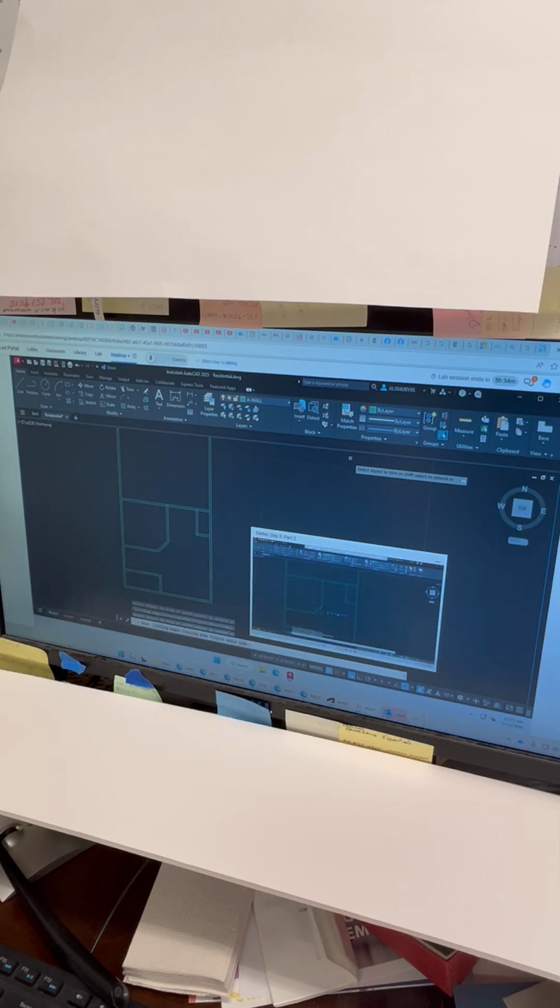Now here's why I did not want you to use the chamfer for the other caddy corner. If you tried to do that with the original 2 foot dimension for the first chamfer distance and a 2 foot dimension for the second chamfer distance, this is not a true 2 foot dimension here. Look at the difference here. That's not the correct width, so that's why I did not want you to do that.